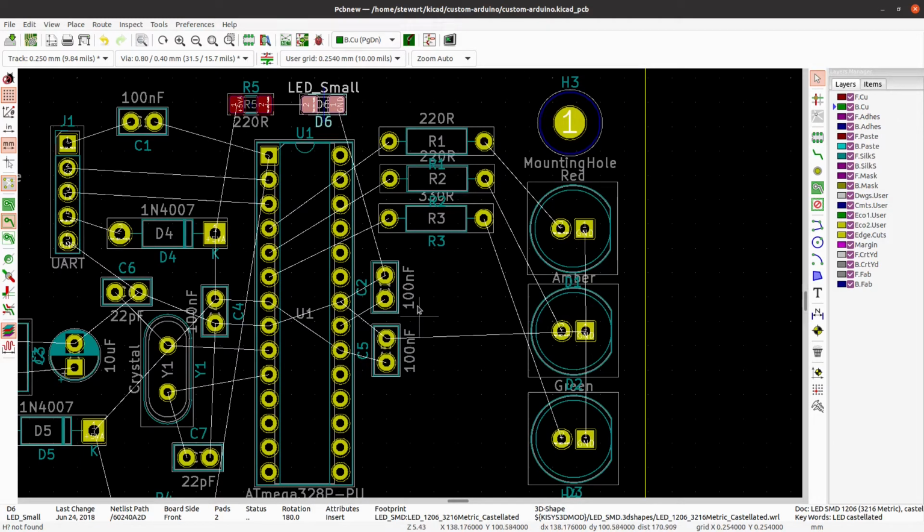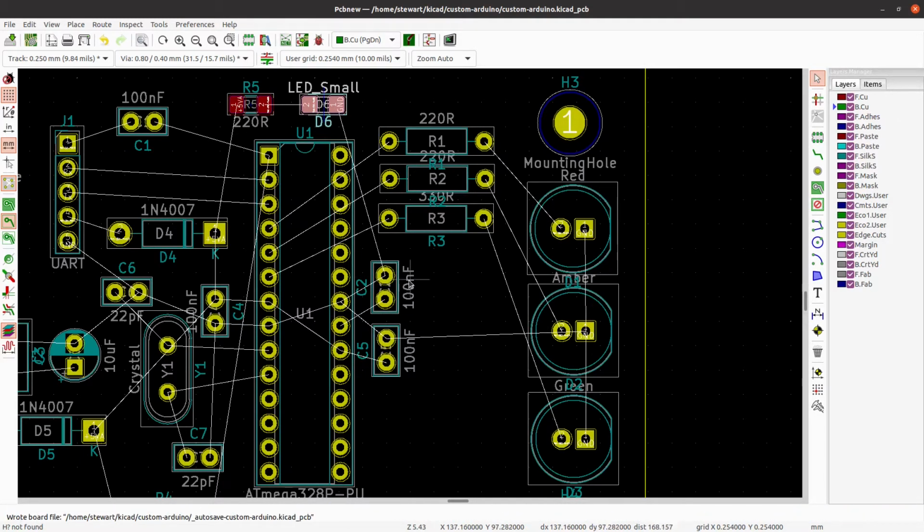And generally I'm not going to connect the grounds because I'm going to use ground planes. I'm just going to use a ground fill to fill up the rest of the PCB, and I'm going to do that on the top and bottom layers. I've done circuits where I've done a ground on one layer and a positive voltage on another layer, but for this I'm just going to use 2 ground layers.